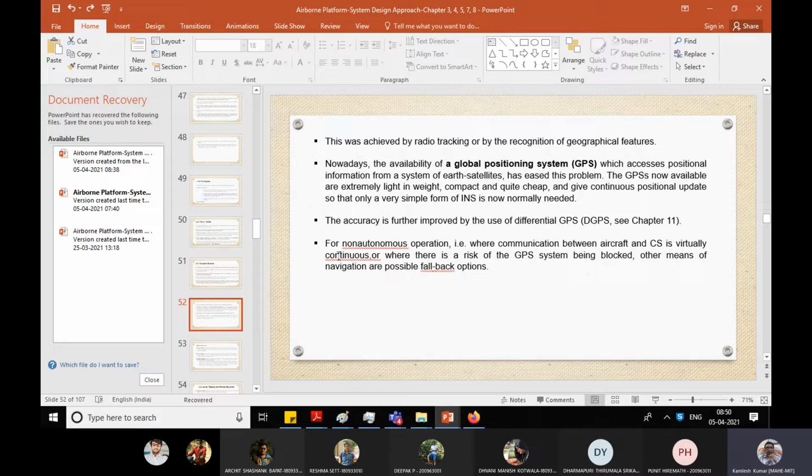So if you want to take control over the communication, the physical system is not going to create a problem, but the software can. If you have control over the software itself, then you can make a secure communication link between the aircraft and the ground control station, at least on the payload side. Because the OEM, having already given the system to you, is of course not creating any problem. But any third party that has a similar communication system or GCS can interfere. They can predict that information and pass their own when they know you are flying those craft.